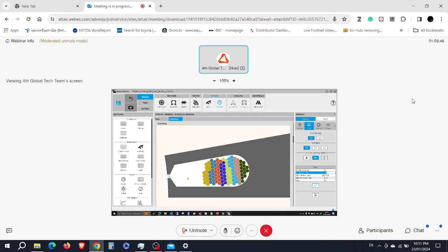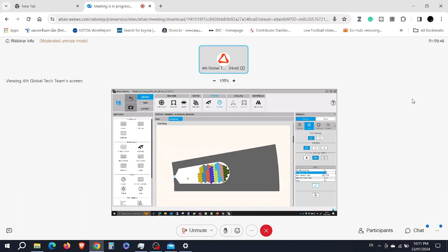Maybe you have a window to reduce the size of your stator. And the diameter of the wires cannot be chosen smaller and smaller. You have to respect the current density allowed for these wires.